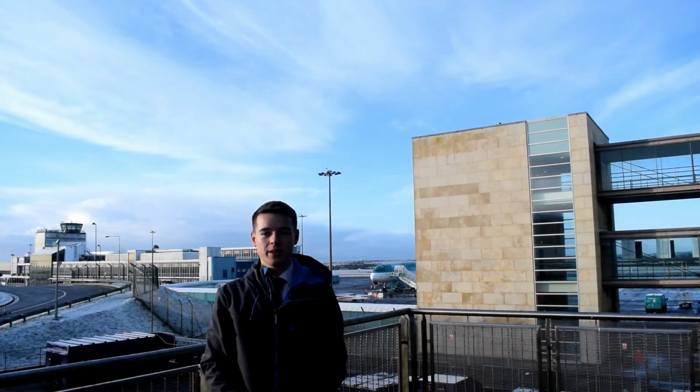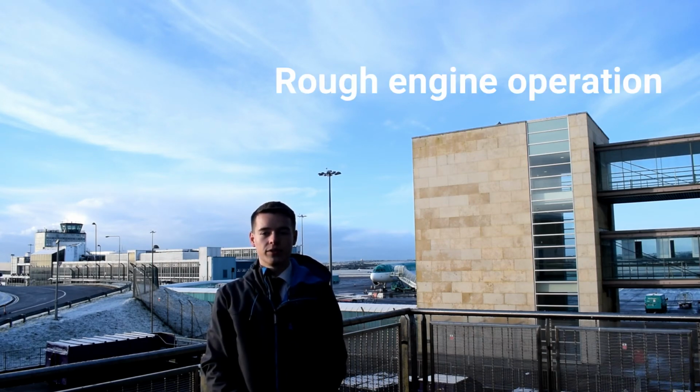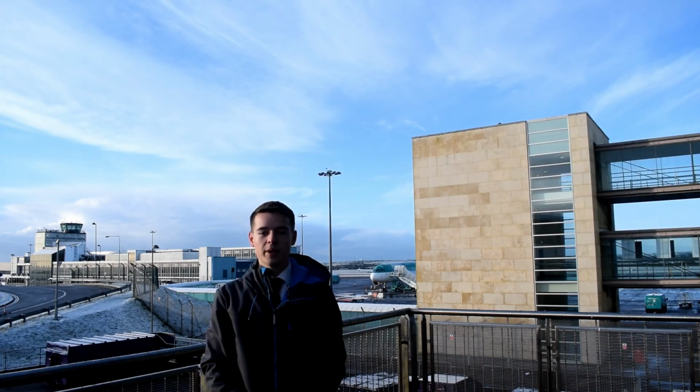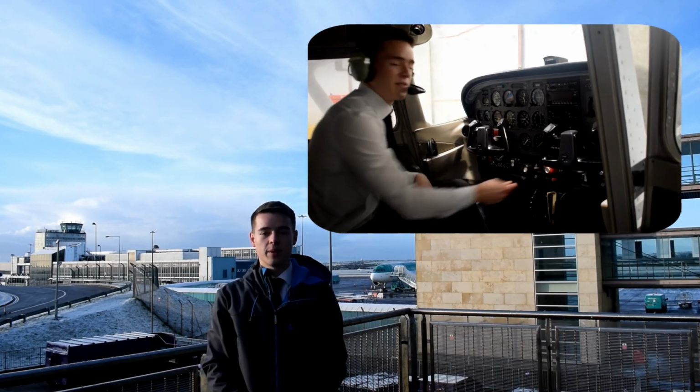The mixture may also become too lean, descending from a high altitude due to excess of air. This causes detonation in the engine, resulting in rough engine operation, overheating, or a loss of power. The mixture must be enriched using the mixture control. By monitoring the engine temperature and enriching the mixture, you can maintain the proper fuel-air mixture.